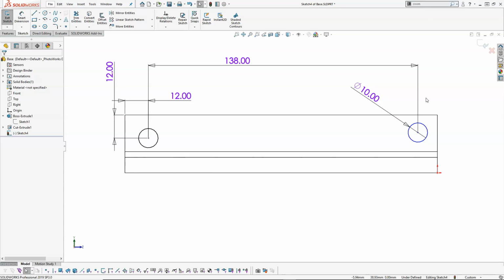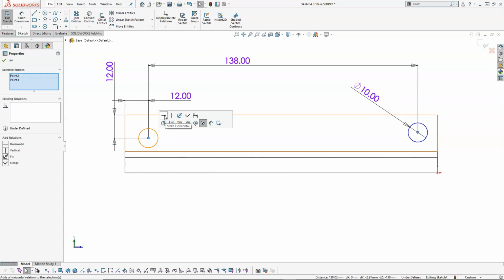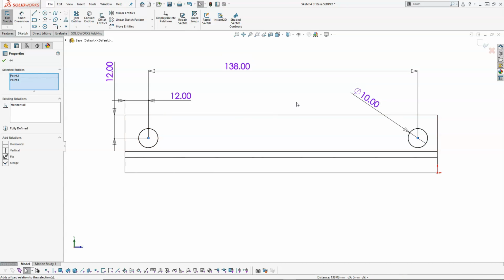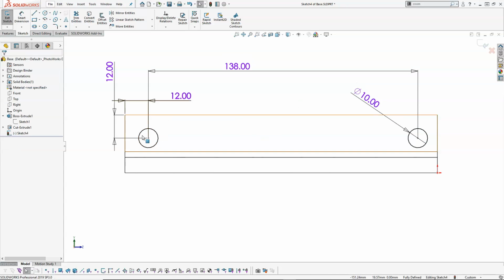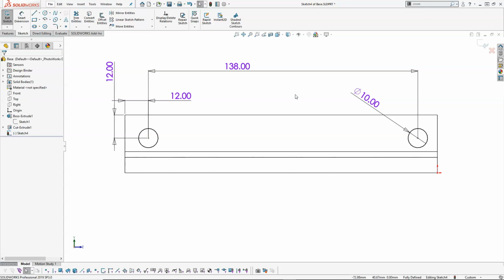So interesting results. So I'm going to go ahead with the center point, hold down the control button and the center point, and then make horizontal. Alright, we can always come back when I select that center point. I'm going to see the horizontal, and I can always delete that and make the adjustment later, since it's not quite lining up visually, but our dimensions and the callouts are supporting our geometry.